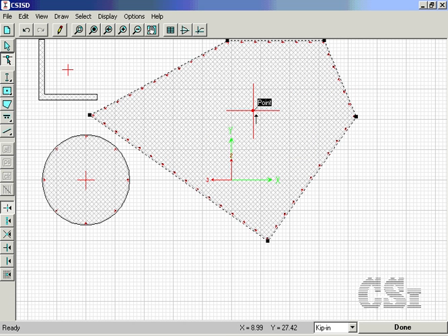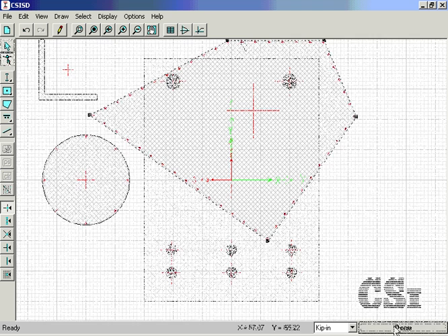At this point, it should be noted that all three of the drawn shapes constitute a single section, and though one of the shapes is steel, the Section Designer utility will calculate properties for Etabs based on the equivalent base material of concrete. It should also be noted that only the member 2-3 axes have meaning for Etabs, as the XY axes shown are local references only.